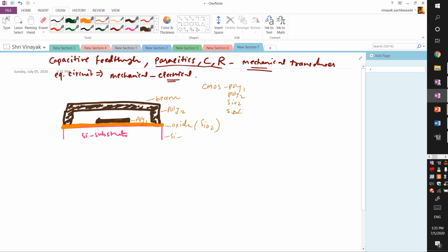So let us understand where the feed through capacitance is. So you have this actuation electrode over here, the drive electrode, and then there is this capacitance which is C0, which is inherent in the structure. And in the last talk we've seen that we are going to bias this vibrating element with the polarization voltage Vp through a resistor, and we are going to sense from the same structure itself. So you have this capacitor to block this DC voltage, and here what you have is the output current, which is the total current. So the total current, we've seen, has one component due to feed through, which is IF, and another component which is IM, due to motion.